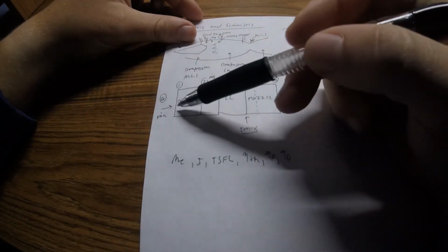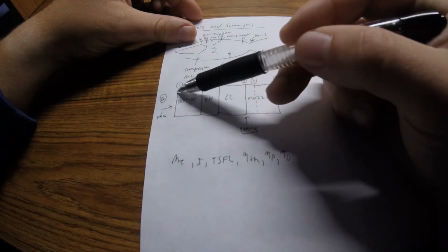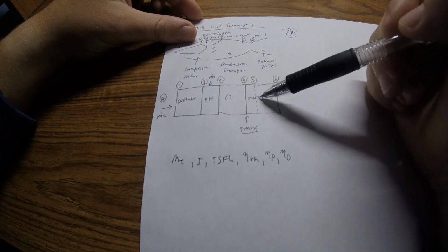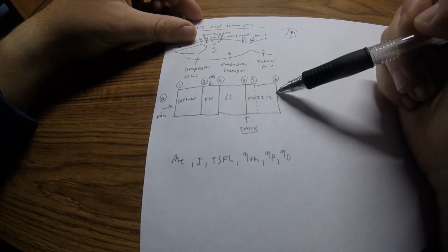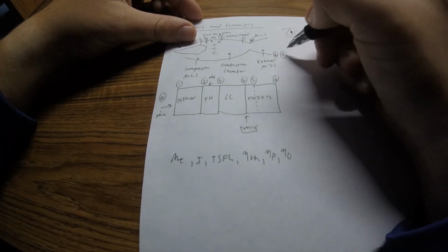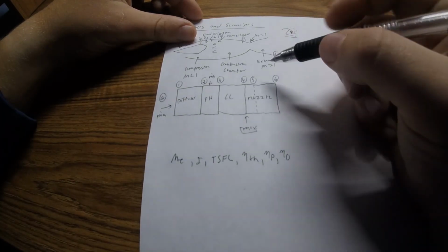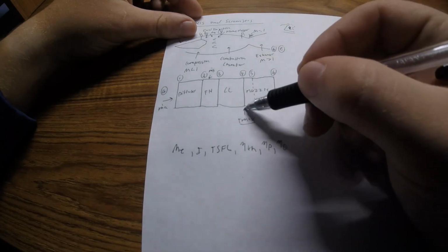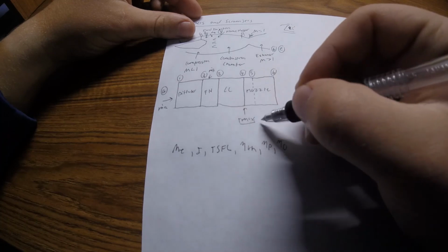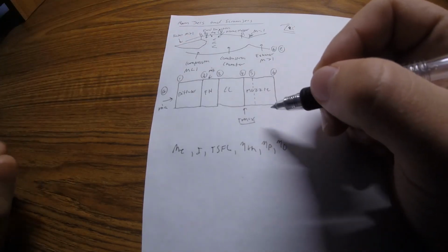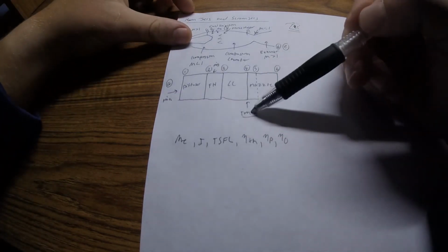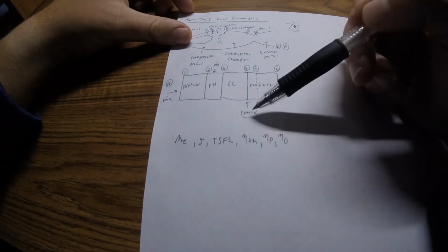So these are all the states right here: airflow in, compressing, diffuser, flame holder, combustion chamber, nozzle, and then out the back of the engine. Here would be state 6, the exit, out here. Your maximum temperature would be at this stage right here at state 4. Therefore, whatever material you're building the engine out of needs to withstand this temperature, because this is where it'll be the hottest.